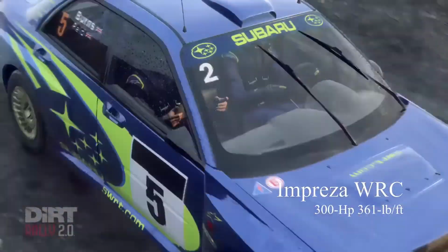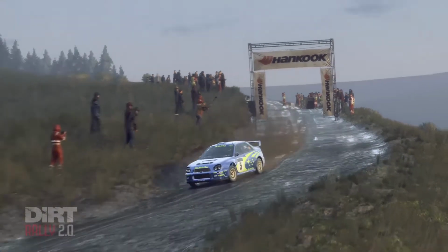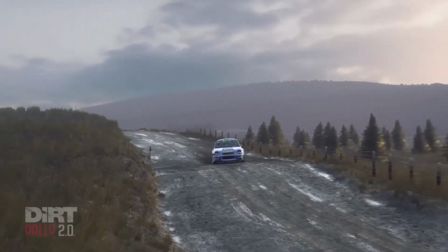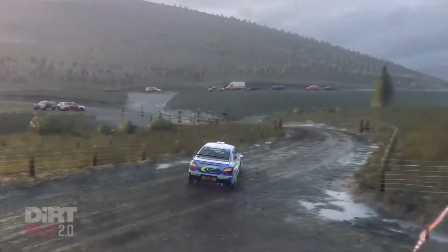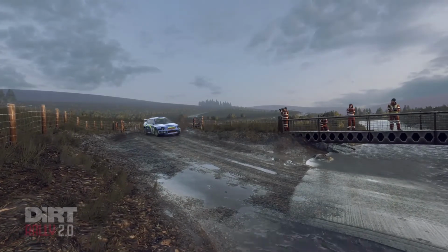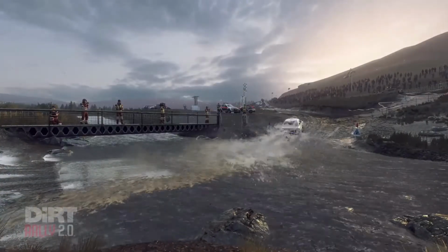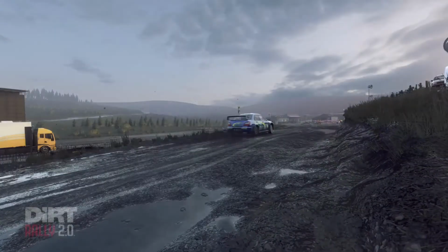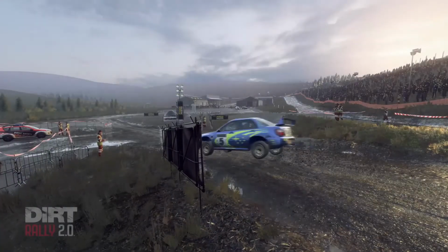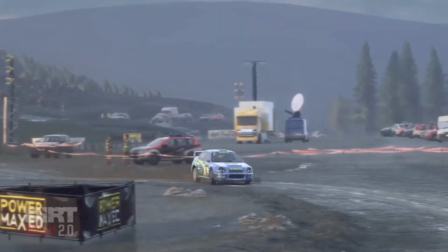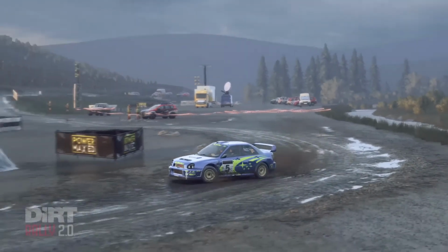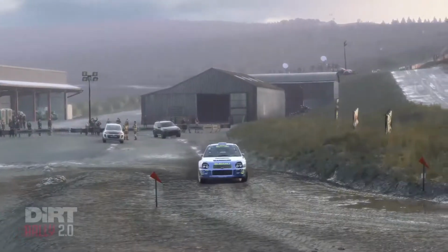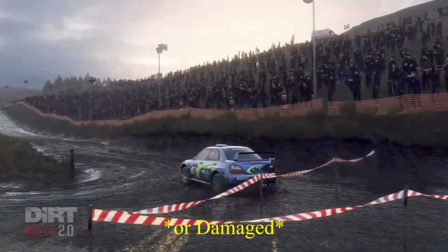Now, if you have a rally build, the vehicle will most likely experience some pretty nasty conditions. Snow, mud, and dirt will clog cooling fins and sometimes an entire opening. Cooling components mounted low on the front bumper or around the wheel well are subject to become completely ineffective if they're not maintained or are located in a poor position. This is why V-mount, top mount, roof mount, and rear mounted components have been used on these vehicles to avoid being clogged by the elements.